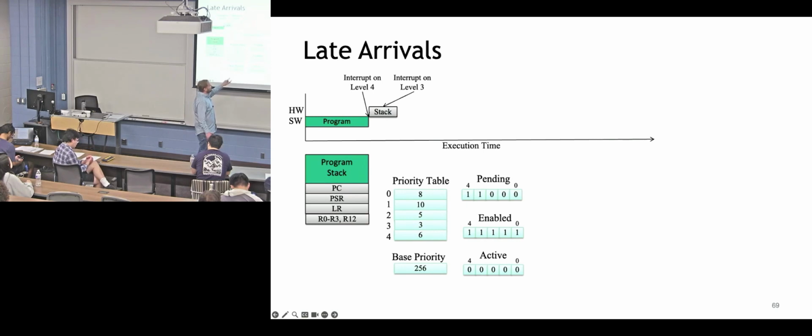Okay, yeah. So now you're going to go just at this last time frame here. It goes through and says, okay, which one's pending, which one has the lowest priority number, most importance, and then it executes that. So the combinational logic of trying to figure all that out, essentially in one clock cycle, starts getting larger and larger and larger. And that's why NVICs usually don't want to have 240 interrupts if you don't need them. Keep it smaller.